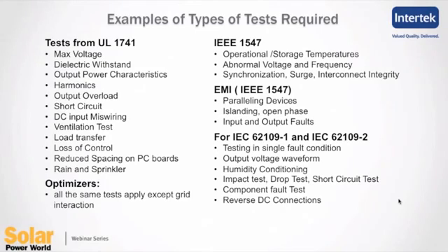just like any other safety standard. Dielectric test is a very common requirement that every product has to meet. There are specific requirements for output overloads on these products, specific requirements on short circuiting, load transfers, loss of control, a reduction of spacing, and as most of these products are installed outdoors in a lot of cases, there are specific requirements for rain and sprinkler tests as well.